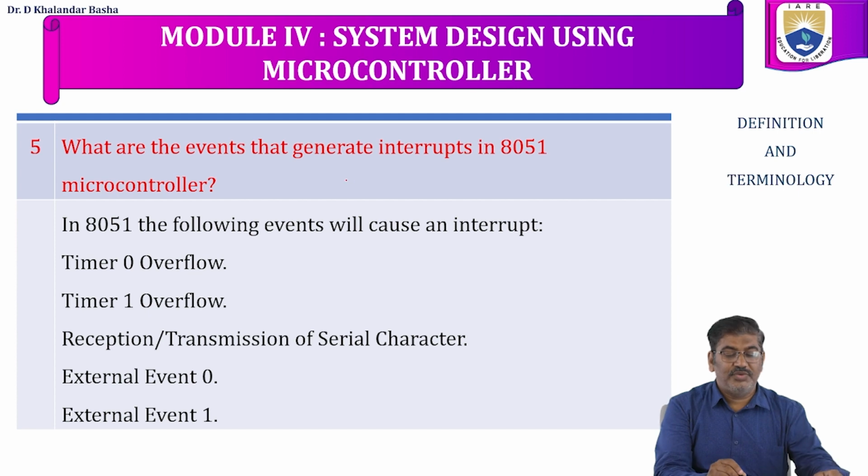So what are the events that generate interrupt in 8051 microcontroller? In the 8051, the following events can generate an interrupt: timer 0 overflow, timer 1 overflow, reception or transmission of the serial character, external event 0, external event 1.